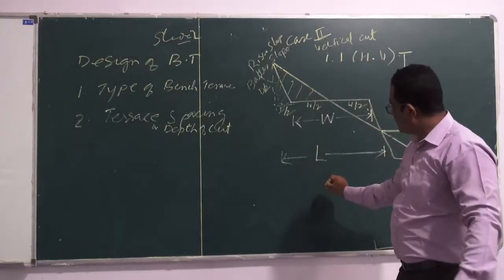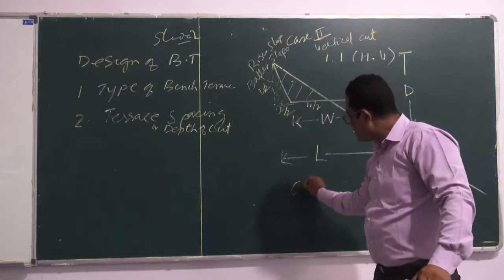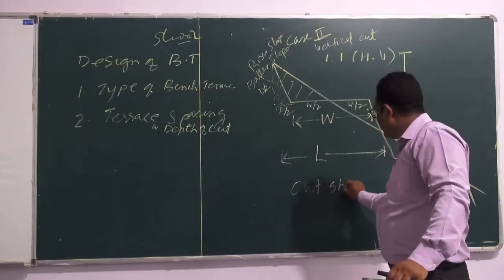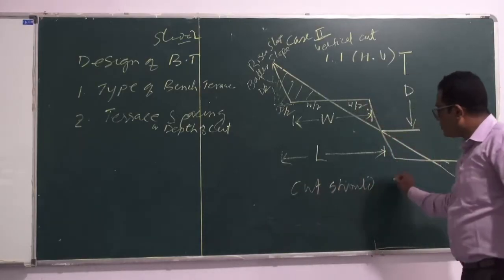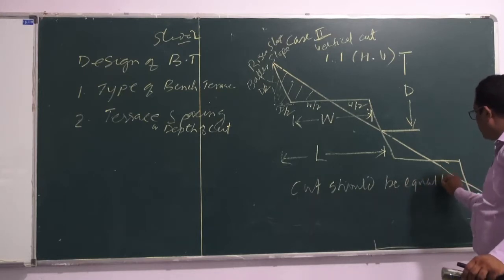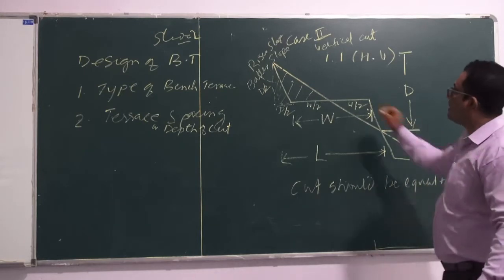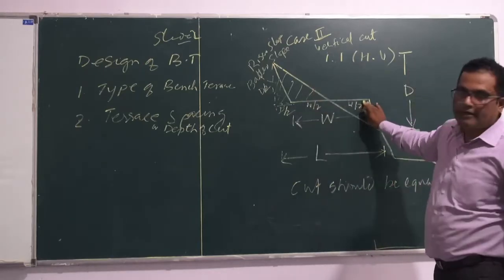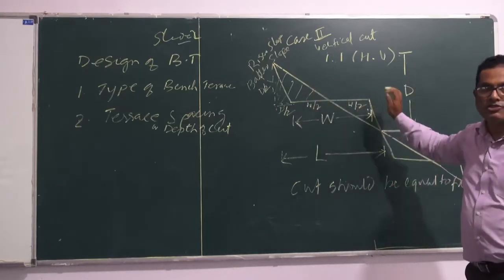And for any bench terraces, one should always remember this: for economic reasons, the cut should be equal to the fill, whatever the cut material is, it is deposited on the downstream side.